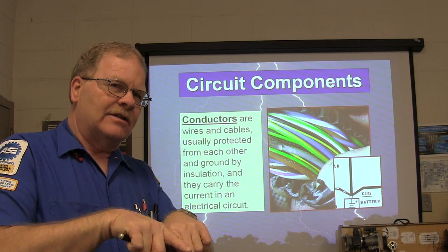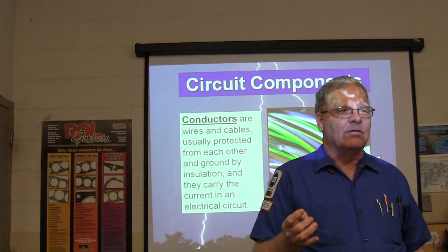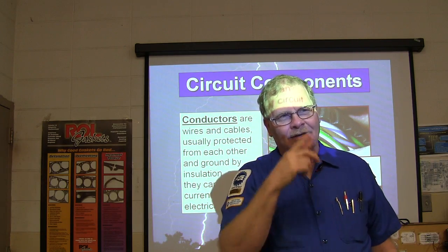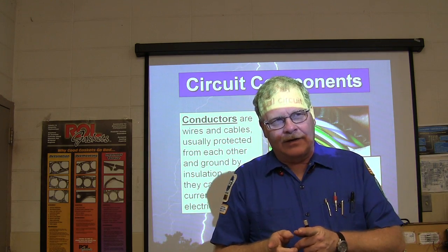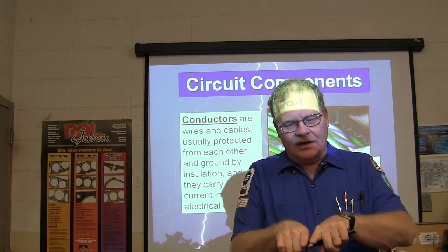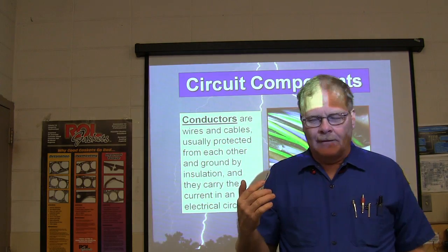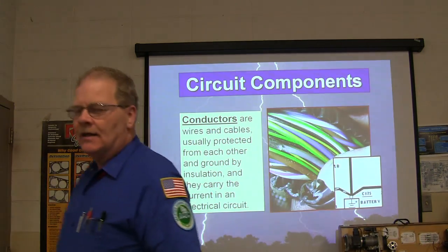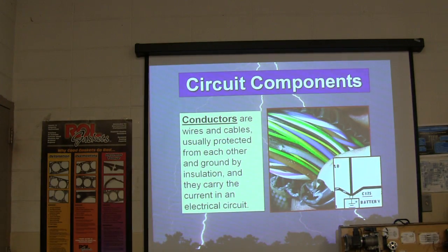And if there's another one laying next to it, like spark plug wires on a 350 Chevy or a 302 Ford, you can actually run your spark plug wires, to 5 and 7 on the Chevy, or 5 and 6 on the Ford. If you run them right next to one another all the way to the plug, the one that's firing ahead of the other one will induce current, or actually a spark in the other one. Even though there's nothing to jump through, it induces it because that magnetism is going to create a spark. Then it can fire, for example, the spark plug that's right behind it is going to make it fire early, and it can actually damage things. But that's why you got to run them with a bunch of other wires in between them instead of right next to one another. That's induction.